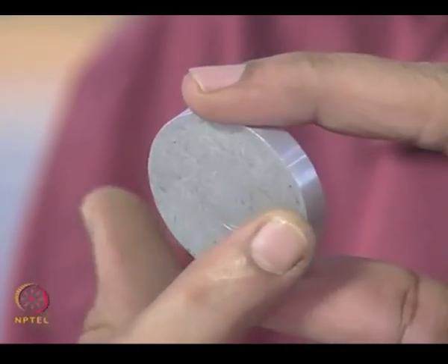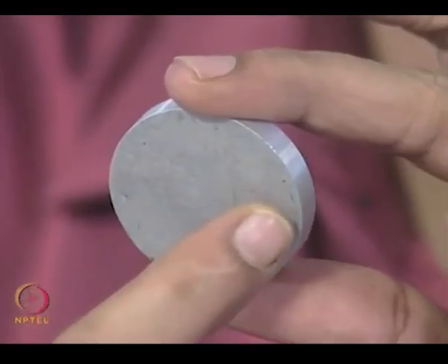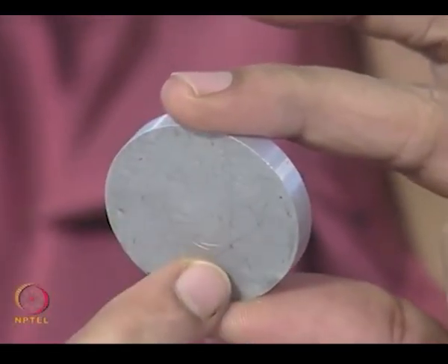In fact, if I take a circular disc like this, you cannot solve it from strength of materials approach. You need to go to theory of elasticity, because of the diametral compression, plane sections do not remain plane before and after loading. So, you have to necessarily go for theory of elasticity, and fortunately from theory of elasticity it is possible for us to find out a closed form expression. That means, if you specify x y, you will get this kind of value for all points in the domain except the load application points.